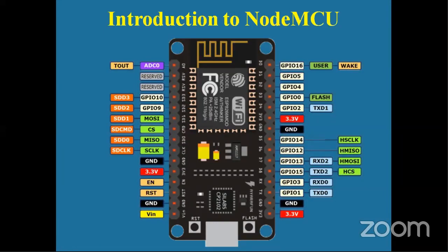But the only thing, when you want to upload the code, you have to select from the tools which board you are using, and from there you have to select NodeMCU, and then you have to click on the upload button. It will start uploading it to the microcontroller.